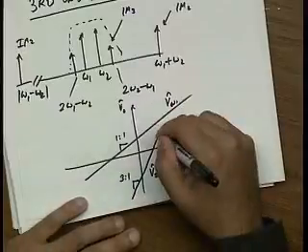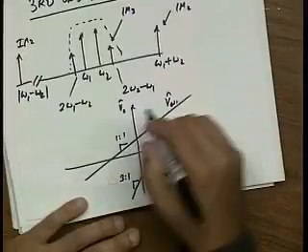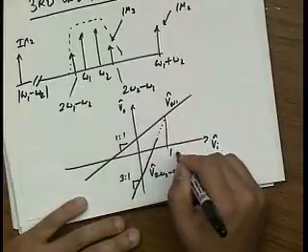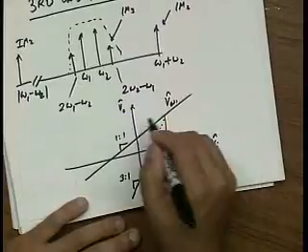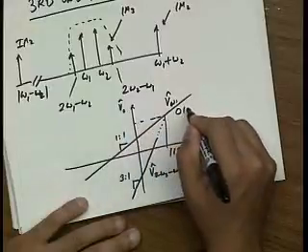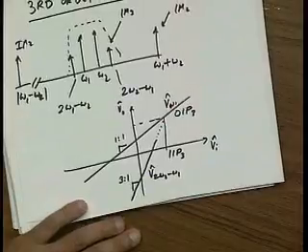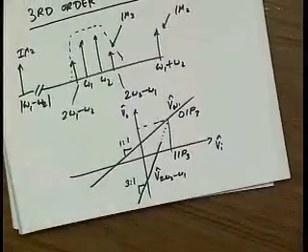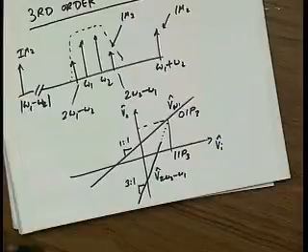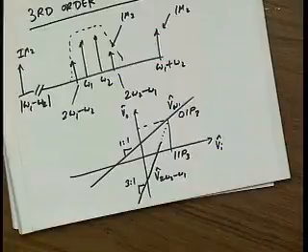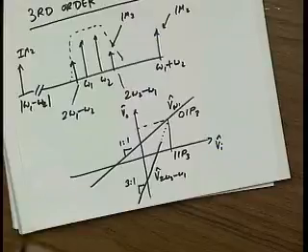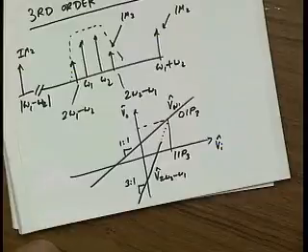And again, I can define the intercept point. I call this my input IP3 point, and this point my output IP3 point. And again, IP3 is the way you typically specify. If you go look at a data sheet for an amplifier, they're not going to tell you what IM3 is at some power level. What they will tell you is the IP3 point. And from the IP3 point, you can calculate basically where you can operate your amplifier. How much distortion can you tolerate?